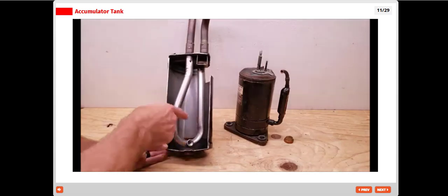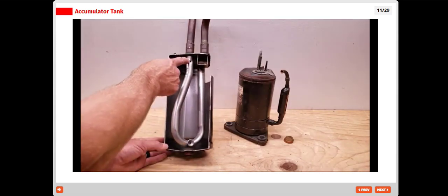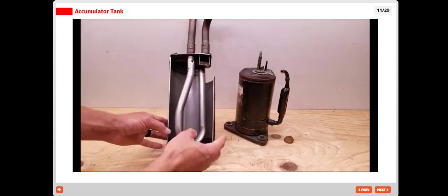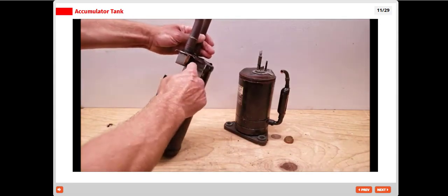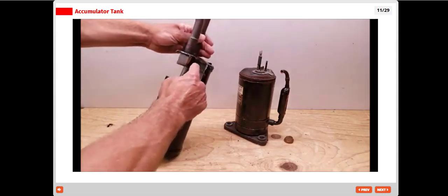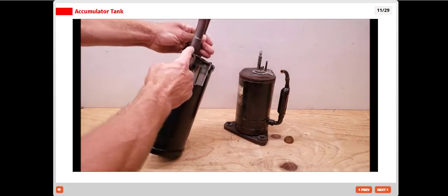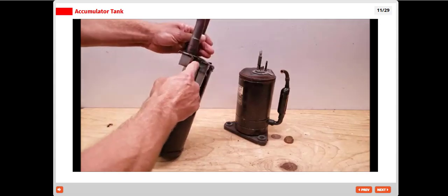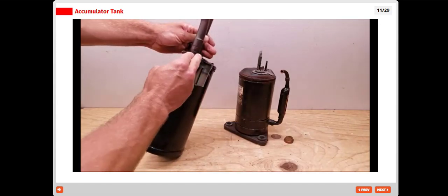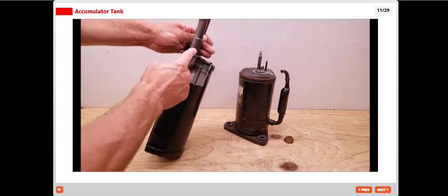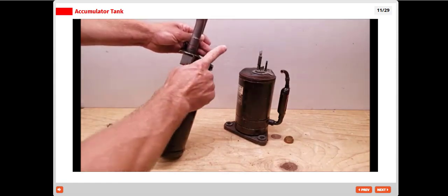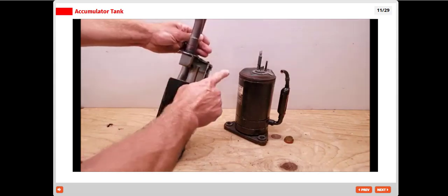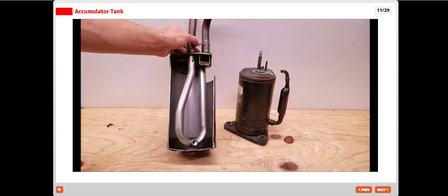So you have that, and then you have this other little hole right here for vapor, and that's going to help the vaporization. But your main vapor inlet to the compressor is being sucked up right here. So this tube and this are completely separated. So this box is only allowing the refrigerant to come into the tank this way. So this is always above that or over in another direction above that.